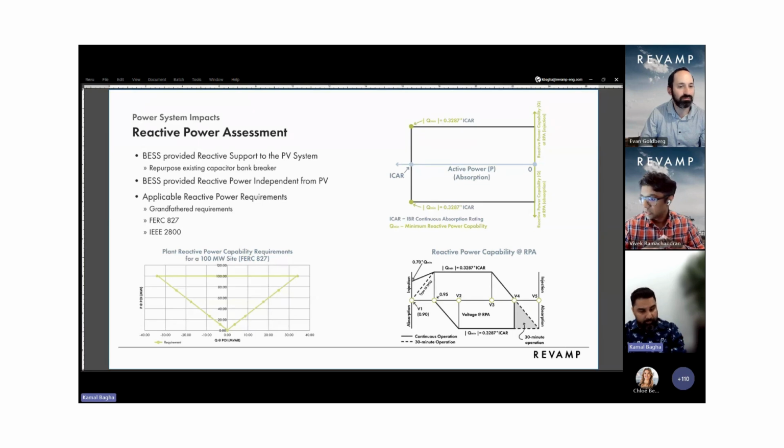Yeah, real quick, Vivek, on that point, what we want to just make sure that everybody understands is the sum of parts, the PV system's losses and the BESS system's losses are independent of each other. You can't sum those up and say those are the total losses, because the losses are going through the main power transformer. If you're using a shared one, they're actually I squared R, so they're exponential as they're squared, rather than linear.